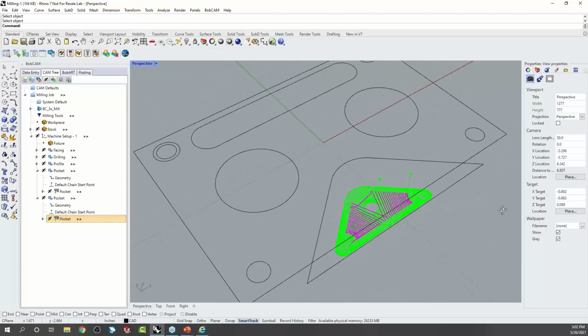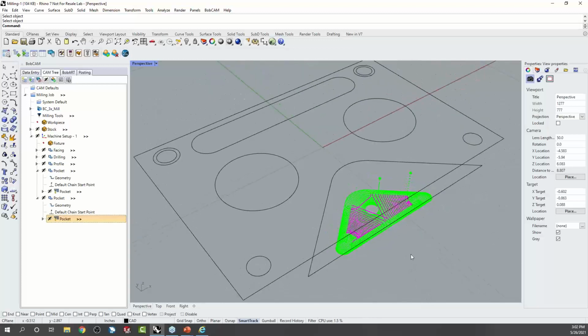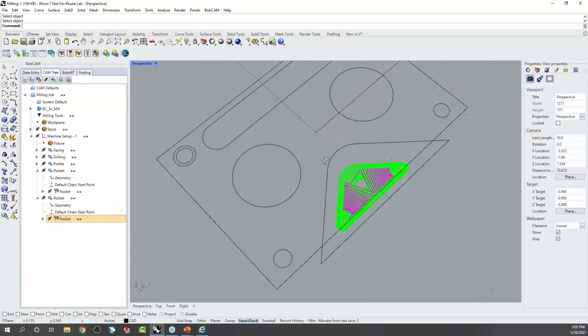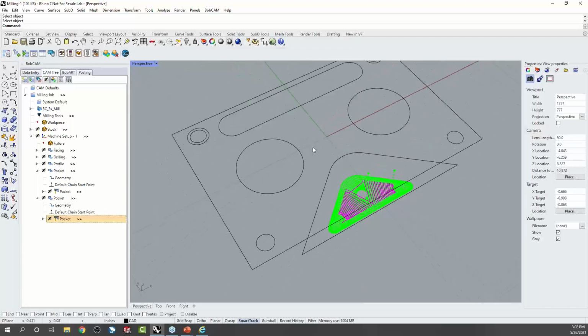I'm sorry, wrong menu there. So that's an example of a 2D pocket. In our Mill Professional, we call it advanced roughing, and you can use this same strategy for 3D machining with step reduction, minimum curvature radius, detect flatlands, operation stock. So that's just a quick adaptive toolpath there and some of the settings. So hopefully that answers that.